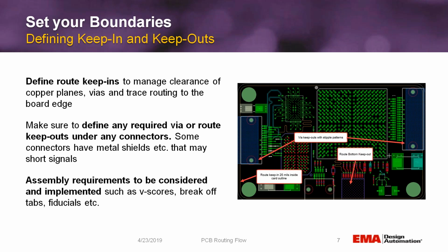You also need to be mindful of your assembly requirements. You might have V-scores, break-off tabs, fiducials, different items on this board that are related to assembly that you need to be mindful of.